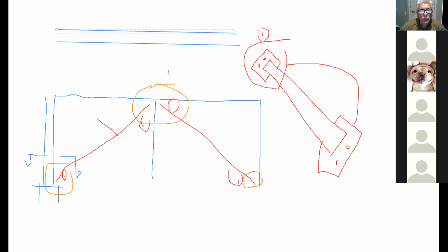So far, so good? And, okay, so here, to support my beam, remember I told you that whatever base plate you put at the bottom, you should put on top. So in other words, I'm going to have a cap plate here of 16 millimeters, okay? Like this.